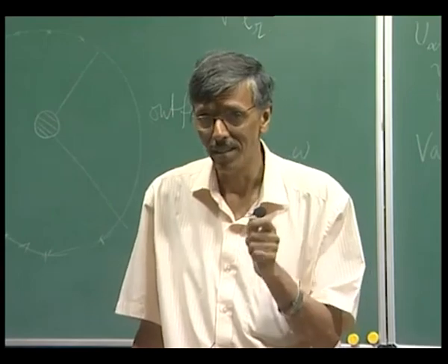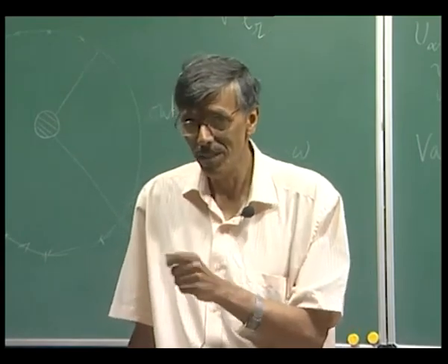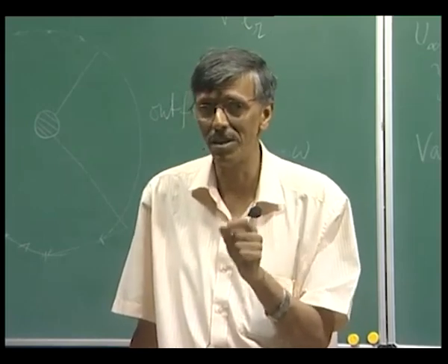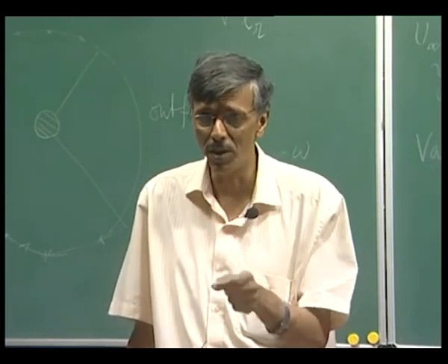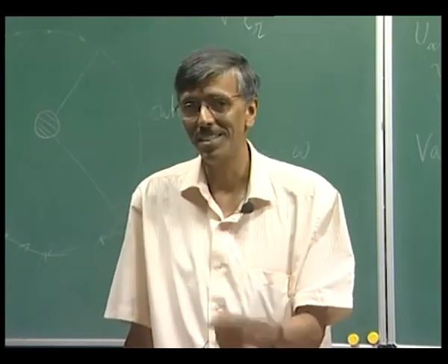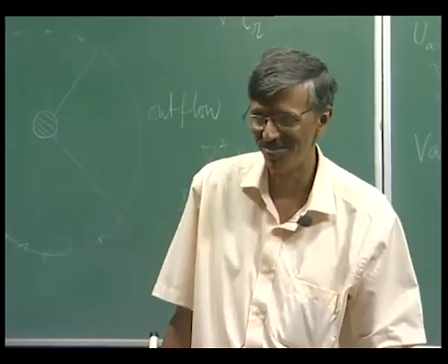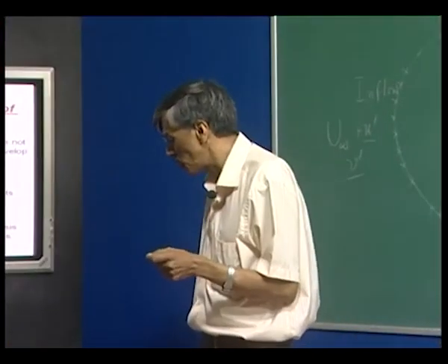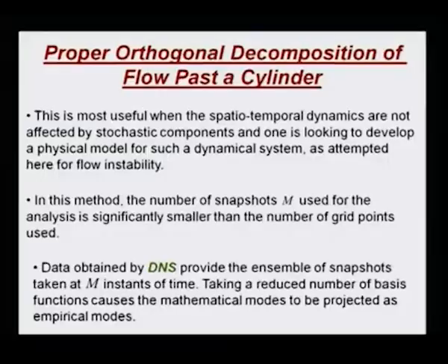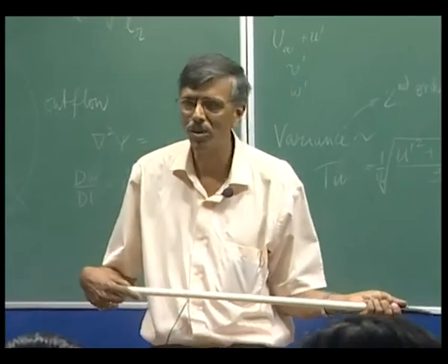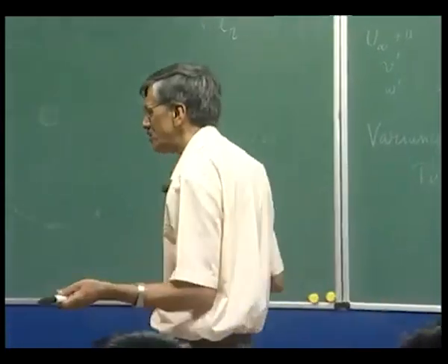Whereas, when I am looking at the stability of the system, you now know very clearly that the disturbances are very important. So, if I am going to use POD for unstable flow, that is going to be much more demanding than using POD for turbulent flow. This is something we have to appreciate. So, when we are trying to use POD to study instability, then we had better have what we call a direct numerical simulation, where we would be getting the solution without making much error, right.